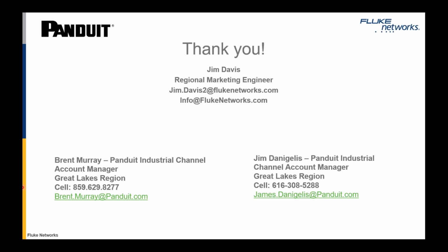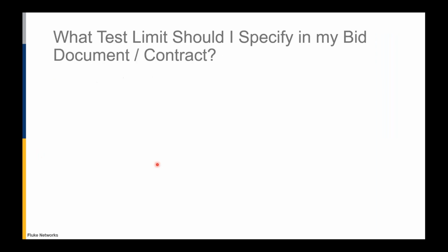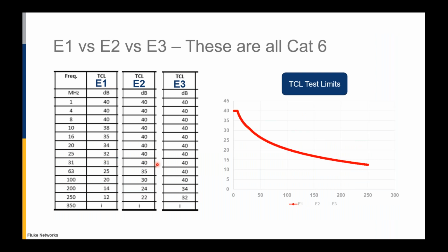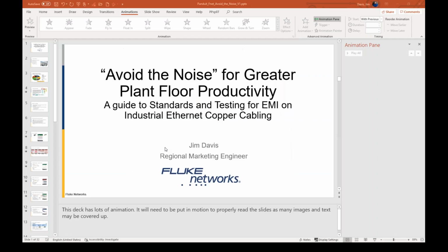When you get into processor-based equipment, switches and other devices that are going to run standard Ethernet, all 4 pairs, 8 pins, that's where you get into the X code. And Jim showed that diagram with the X that you can actually see on the front of the connector. So as you get into processor-based equipment, that's where you're going to see X code. D code's been out a lot longer. X code is newer, right, with the process-based and edge IoT type devices.